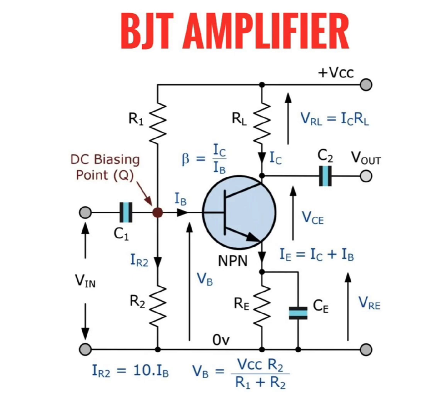Why is the Q point important? The Q point ensures the transistor is not in cutoff, is not in saturation, and operates in the middle of the active region.